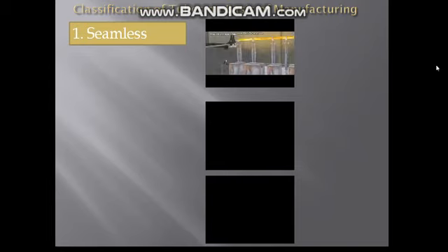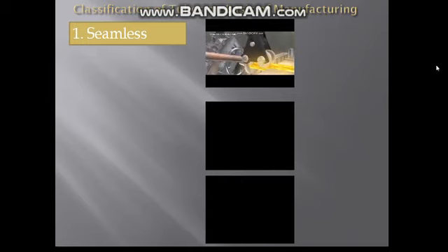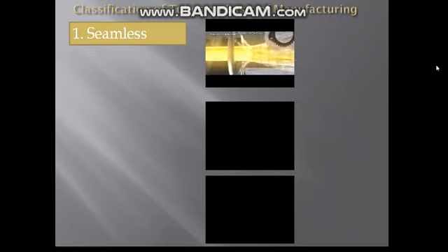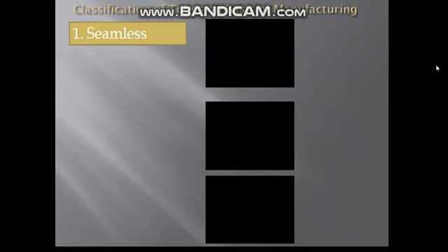Further, annealing process is carried out. Annealing process is carried out to make the tube softer, so that tube can be shaped easily and cut easily. Further, tubes are passed through buffing stage. In this stage, scalar surface of the tube is cleared and also it is made shining surface.